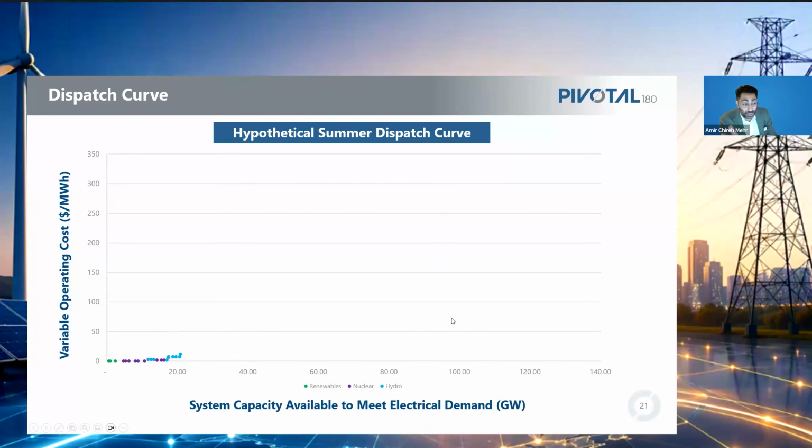Now, that's the world of the sort of must-run dispatch power plants that are typically almost always on, unless there's some emergency, because in California you're not going to see demand much below this, right? A lot of this is base load. It's going to be able to run all the time. But this is when you start to see your conventional dispatchable fossil fuel power plants coming in next. And the first, in this case in California, it may be different from one location to the next, is going to be coal. So why this one coal plant is here and the others there may be a nuanced question,